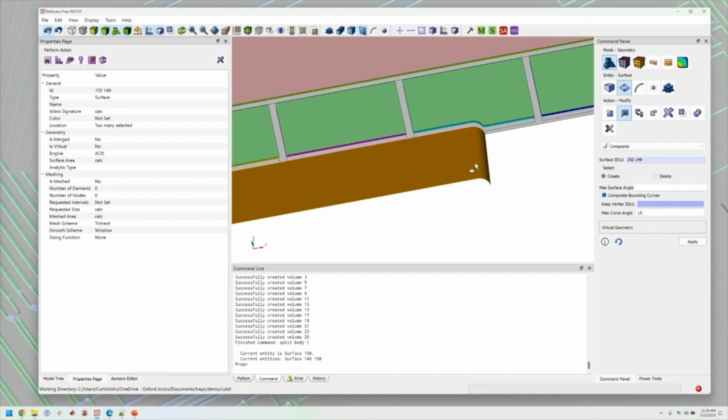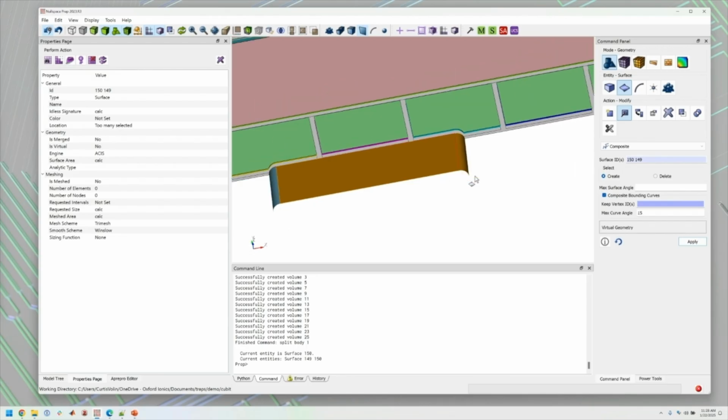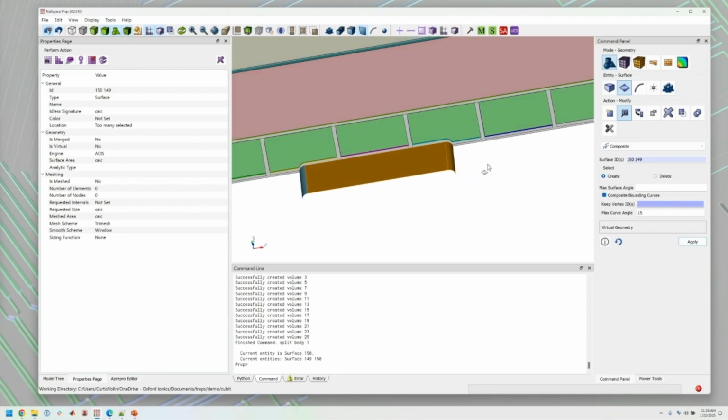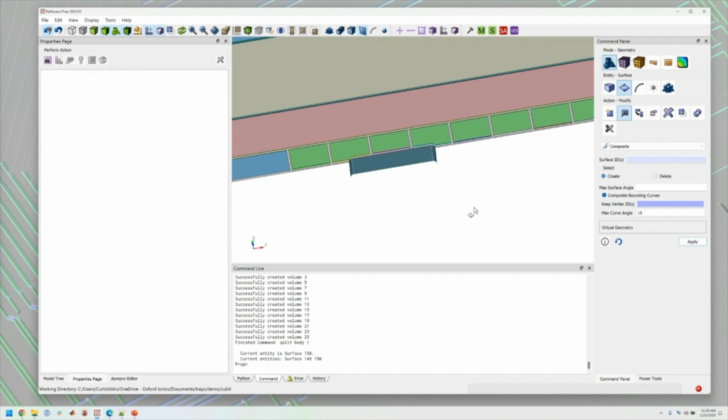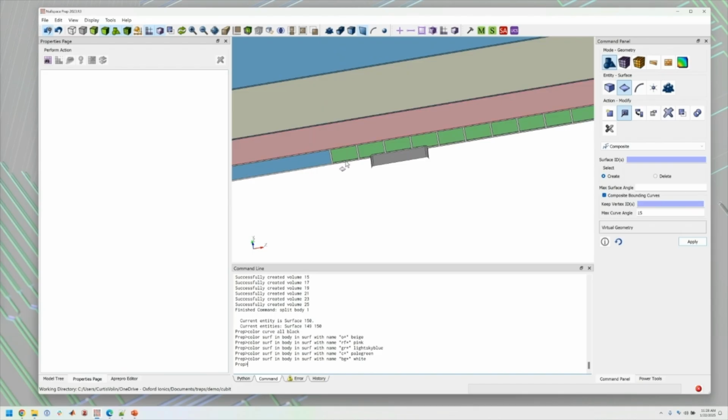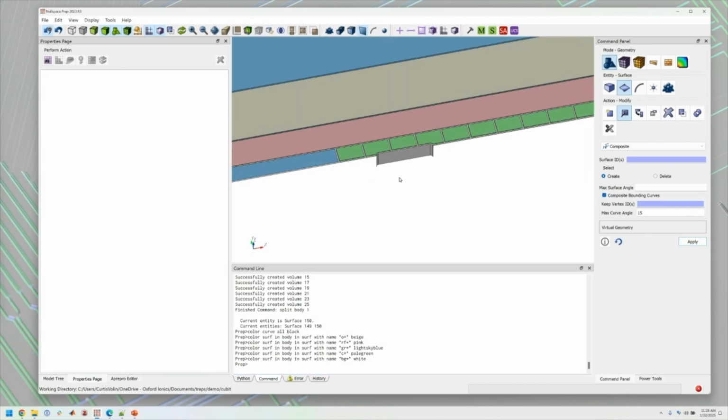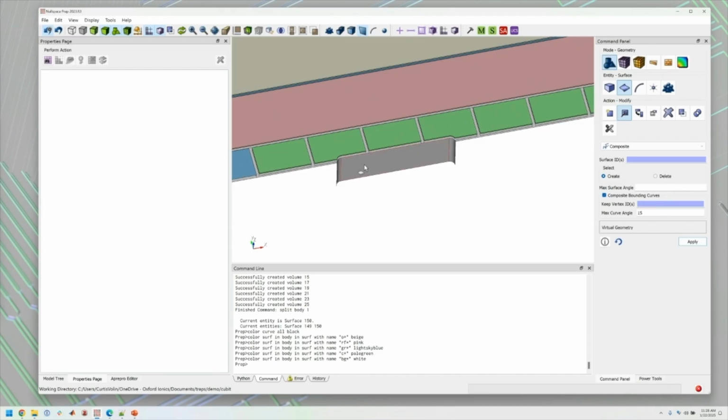And so the small price you pay in terms of solve time from having a few extra triangles is more than worth it, compared to, especially in larger models, potentially having mesh errors generated that are very, very difficult to find and diagnose. So I'm just going to leave those off. And then I can colorize things to make them consistent. So we have pink RF, green and beige for the control electrodes, and this gray color for the lower ground plane.